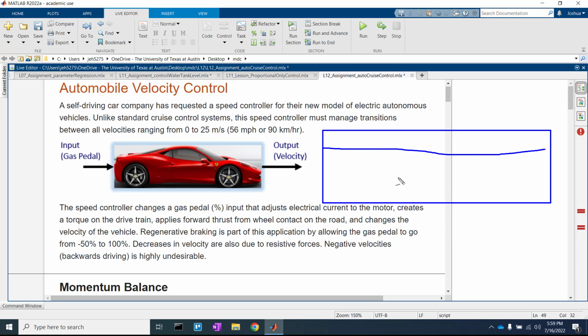If this is our set point, as we were to approach the set point, the error is going to diminish, and because our u is only proportional to some error, so P times some error, the gas pedal will be let off until we reach some steady state below our set point. So what we do with proportional integral control is we look at all this area and we say we're going to penalize it as well, so that we start bringing this up and we minimize that distance until we are right on that set point.